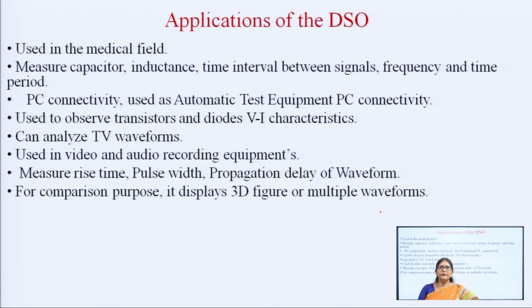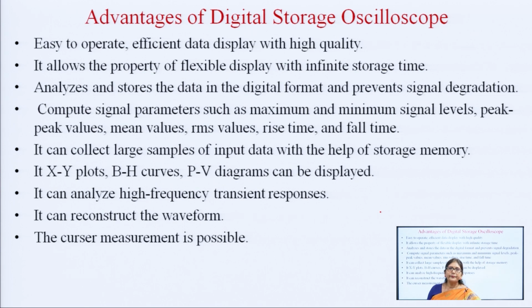Now, the applications of the DSO. We can connect it with equipment, we can analyze the TV signal, any video signal, and 3D signals. We can measure the rise time, fall time or the propagation delay time, and we can see the behavior of capacitors, inductors and other things.